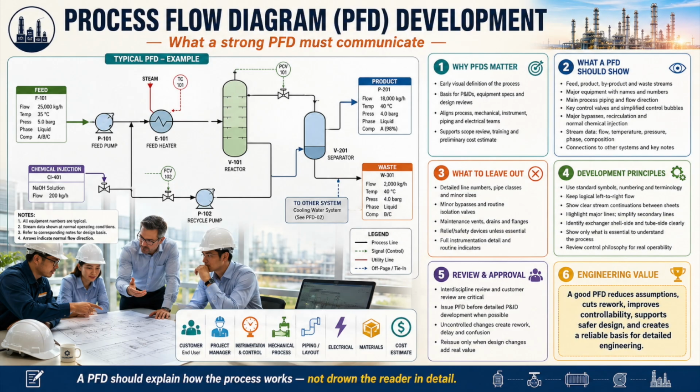Trays, packing, baffles, demisters, filter elements, vortex breakers, and similar internals may be represented when they explain equipment function or influence downstream design. Show control valves and major manual valves only when they are essential to understanding normal process operation. A heater pass throttling valve or a block valve that redirects flow between operating systems may be important.